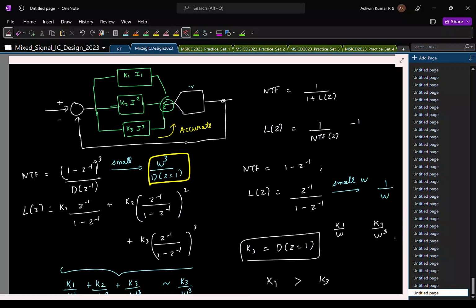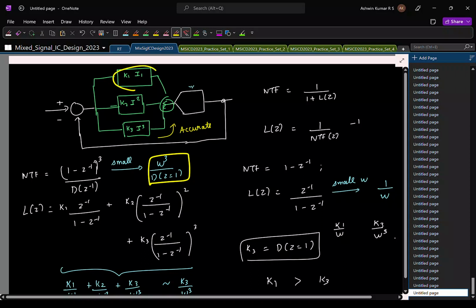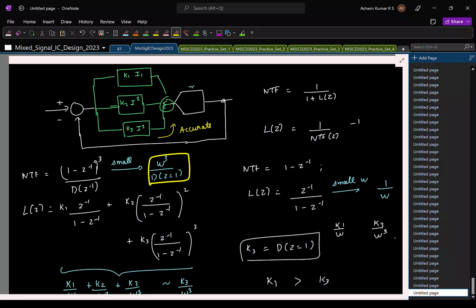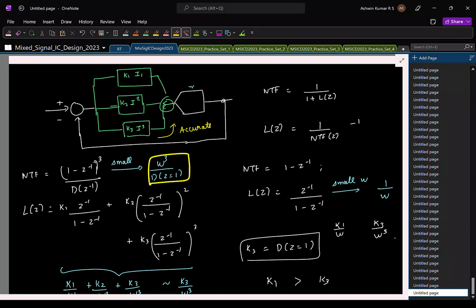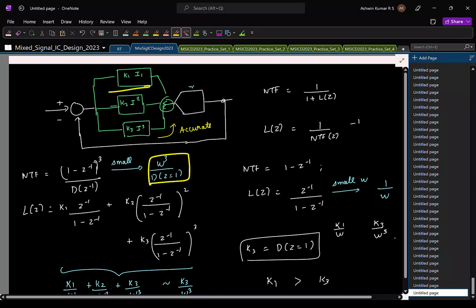But to instantaneously stabilize the feedback loop, you want this path to be much faster. So, I mean, you can think of it like this. This is adding a 0. The proportional path will add a 0 usually, right? You want to keep the 0 at a sufficient frequency so that your loop is stable in control theory. But intuitively speaking, you want the fast path to be dominating the slow path for instantaneous changes.